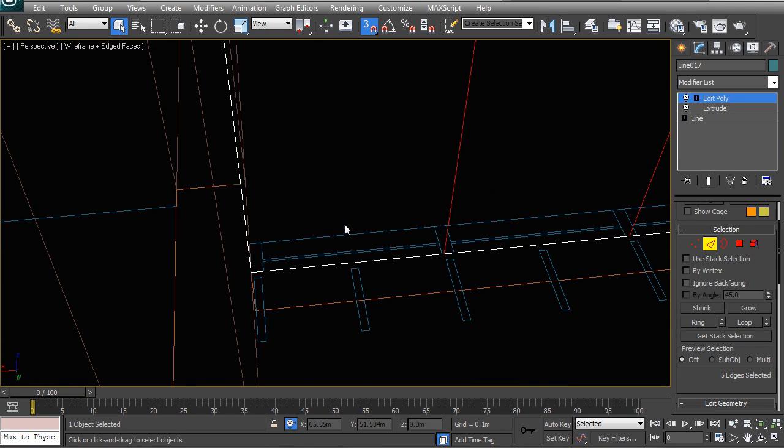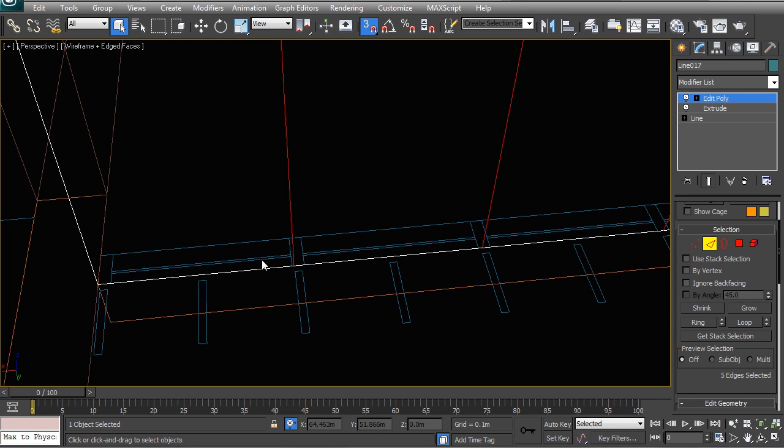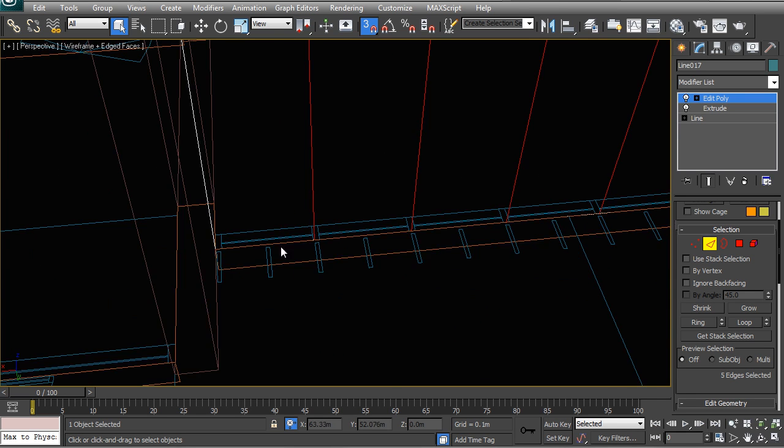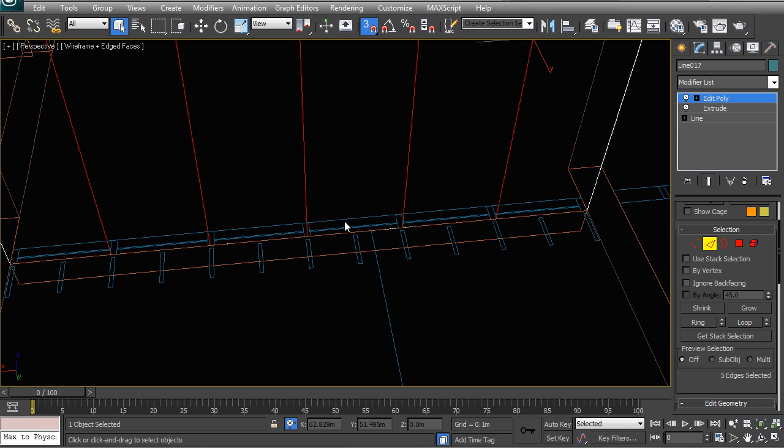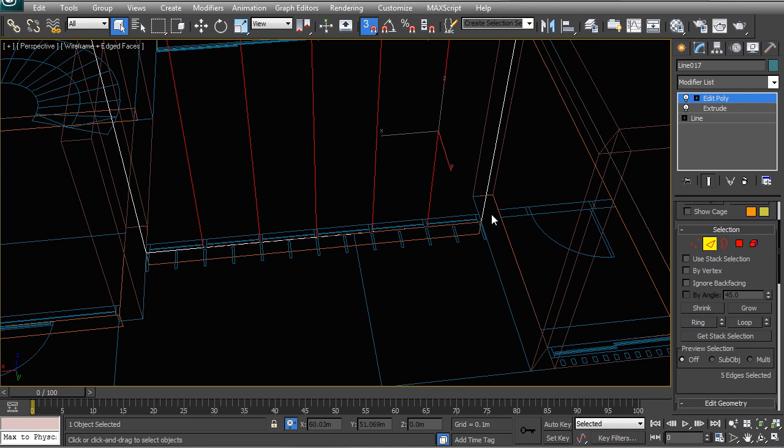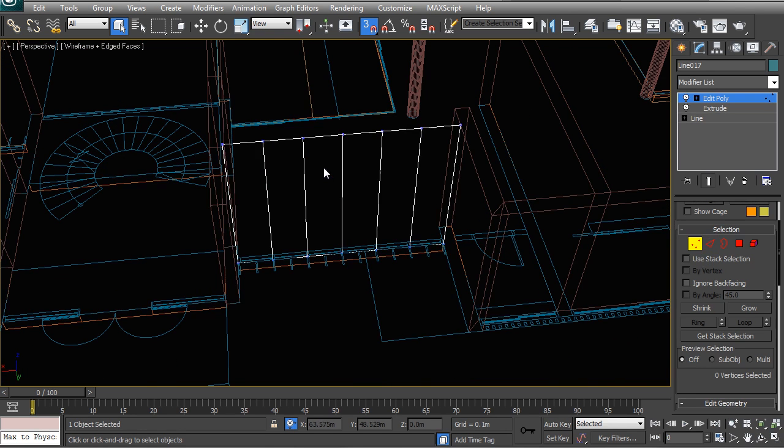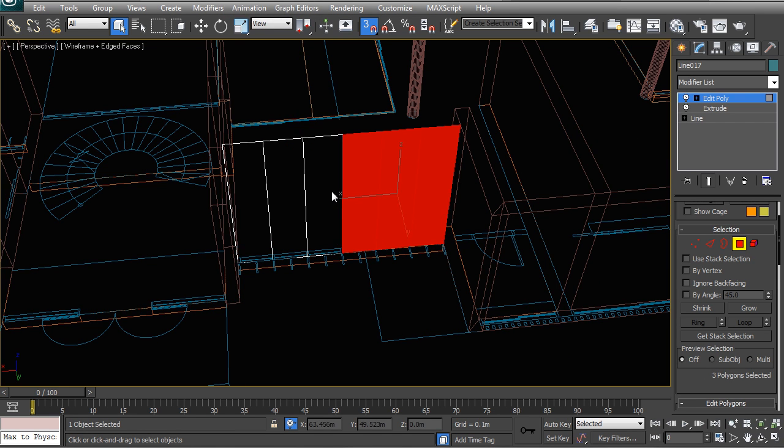Now, you will see that these lines don't exactly line up, because here we have the outside, and once that interpolation happens over these 6 panels, they aren't exactly evenly spaced. So you can manually move everything into the right position before you add your segments and make it really neat and tidy. But what I'm showing you here is a much quicker, rougher way, instead of going the proper due diligence way.